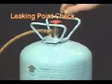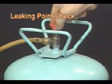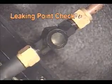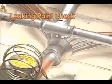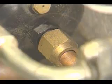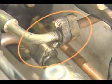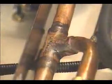When the refrigerant lacks after driving for a long time, refill the refrigerant and drive, because there's a tiny leak in the system. However, if the refrigerant lacks again soon, find the leaking point for repair, because it means a serious refrigerant leak. Since the serious leaking points are polluted with refrigerant and lubricant oil, it can be easily found by eye check. As for the leakage check, check the fitting and welding points first.